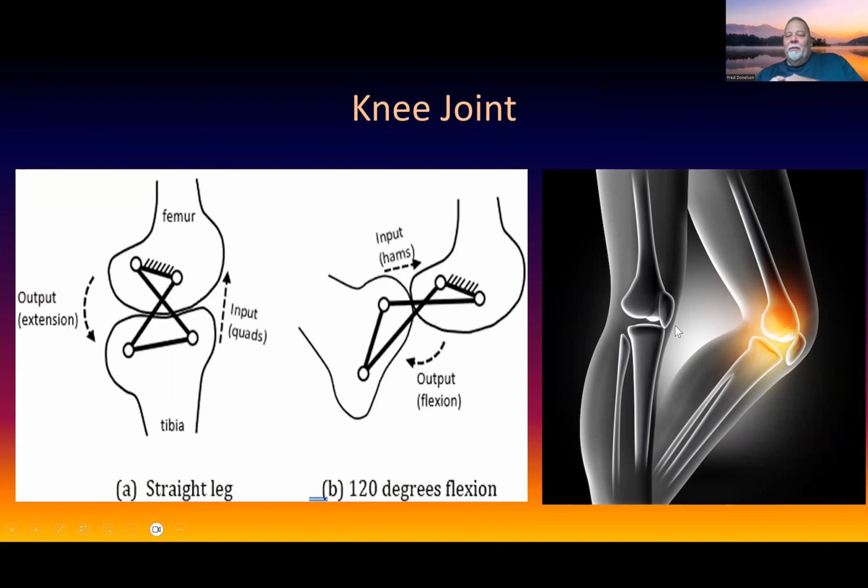What happens is, when they first started trying to make legs on robots, if you try to make the joint like just a regular joint where it can go both directions, it chatters. It will actually break down and won't work correctly. But this kneecap stops that chattering.